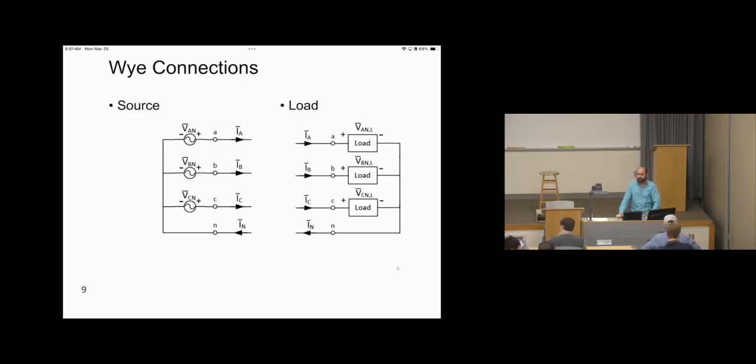So as we discussed last lecture, there are 3-wire or 4-wire systems for three-phase systems. Three wires is where the neutral does not exist, or the neutral conductor has been removed, or four wires where the neutral exists. Then we discussed 4 line currents, IA, IB, IC, I neutral, and 6 voltages, 3 line-to-neutral and 3 line-to-line. VAN, VBN, VCN are line-to-neutral voltages, and VAB, VBC, VCA are line-to-line voltages.